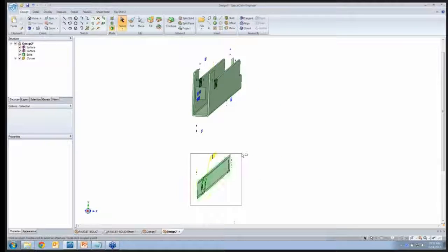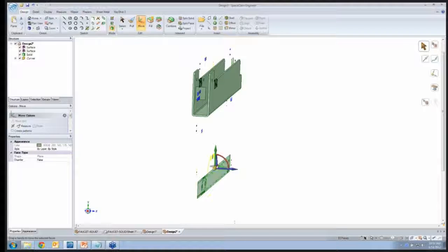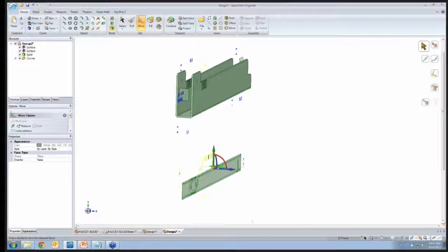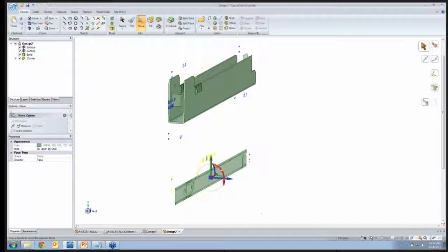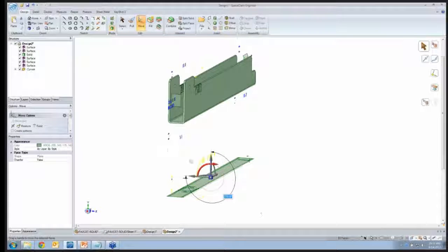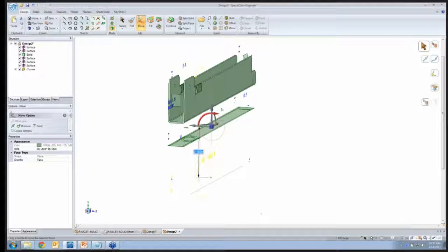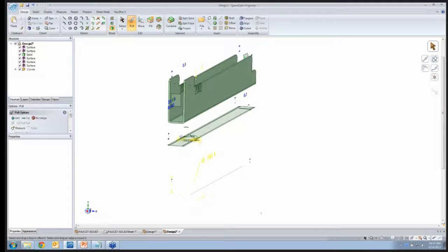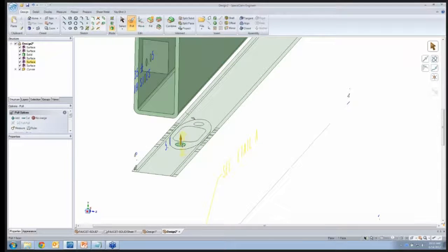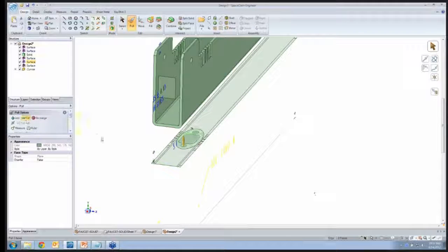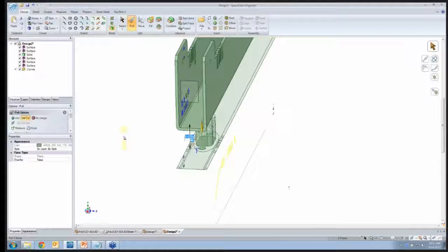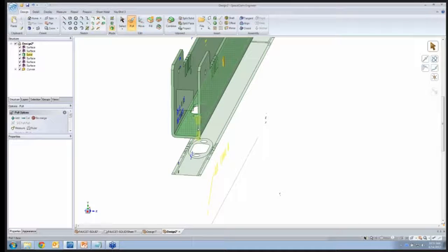There's still a couple features I need. There's still a couple things in the mix from this bottom sketch that I'll need to utilize so as to get this thing looking correctly. And I'll move this sketch up just a little bit to make it easier to see when I make the cut. I've got some holes, 3 holes, 2 circular and something that looks more like a trapezoid. So I use the pull tool. Pull that straight up and make my cutout. No sketches, just utilizing the data around me.